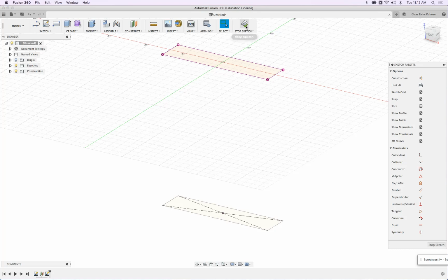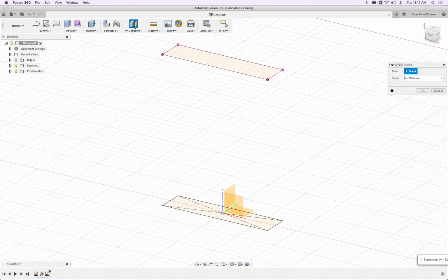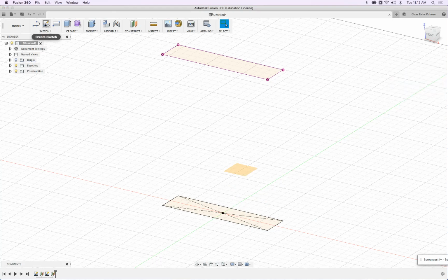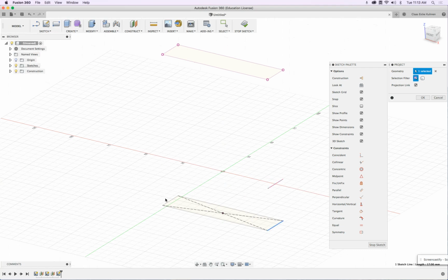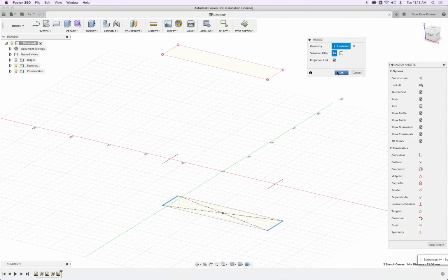And this will require another offset from the ground again up. Let's say 26 millimeters. Okay, very good. We make a sketch on here. We will project only these left and right edges in. This is all what we need, because this actually remains the same, and now between these endpoints we have to create our arcs.